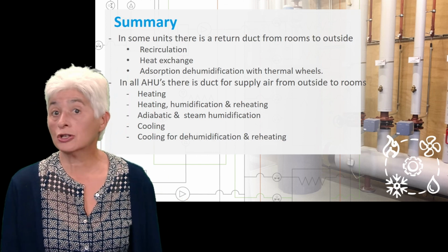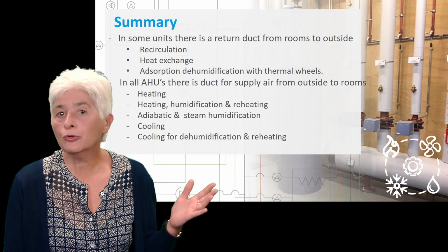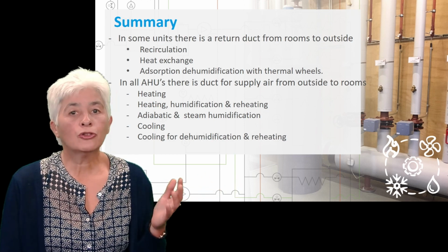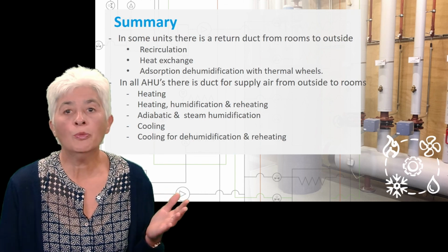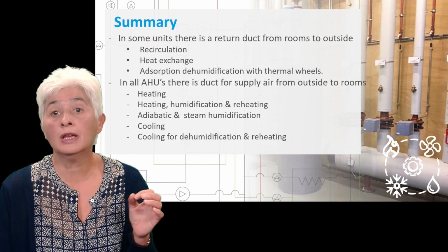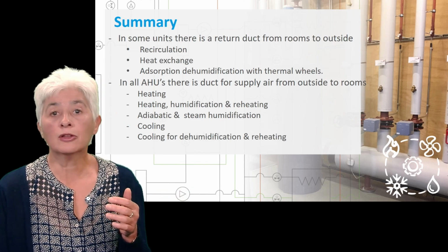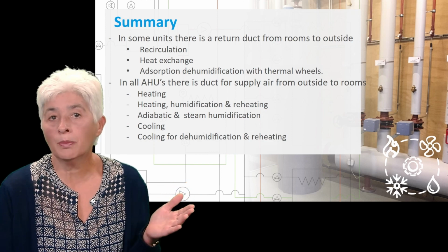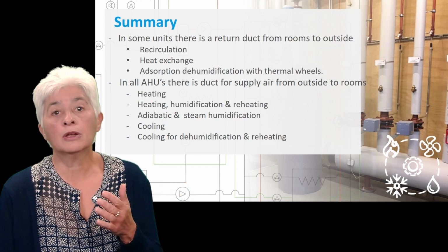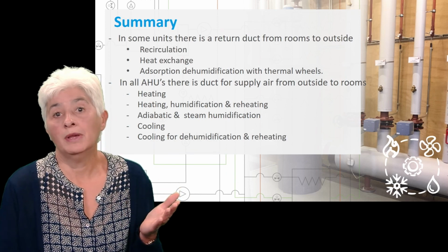Note that this lecture was about the most extended air handling units. Of course, there are smaller ones, in which only a part of the processes is done. For instance, in homes in Europe, generally only the heat recovery part is done. In moderate climates, it may be that only the heating part is present and that humidification is not applied. In hot and humid countries, only the cooler and the second heater will be present.